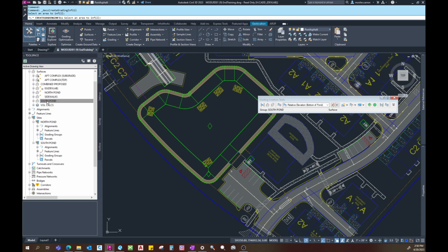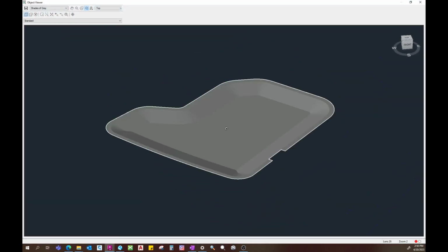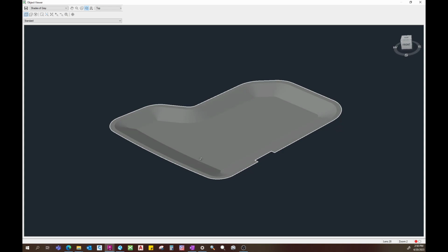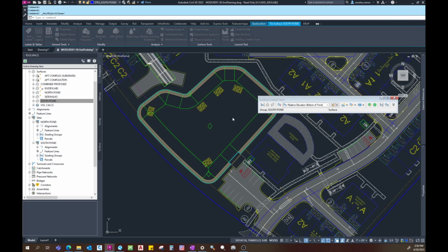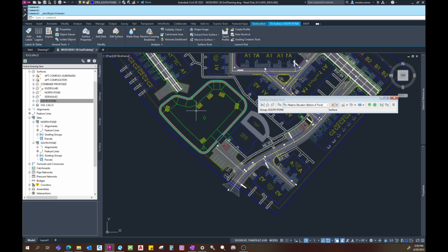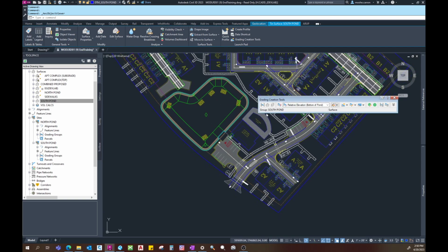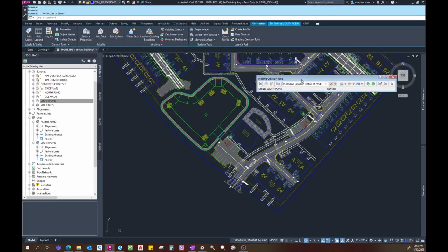And if we jump again to, and let's escape, select it, take again a look at our object viewer, and we can see this time that it has now completed our detention pond. But there's one final step that we want. As is the circumstances in many design problems, we'll want to have a targeted surface, either the existing surface that we'll want to target for our excavation, or possibly a future stage of the project for proposed or temporary construction.